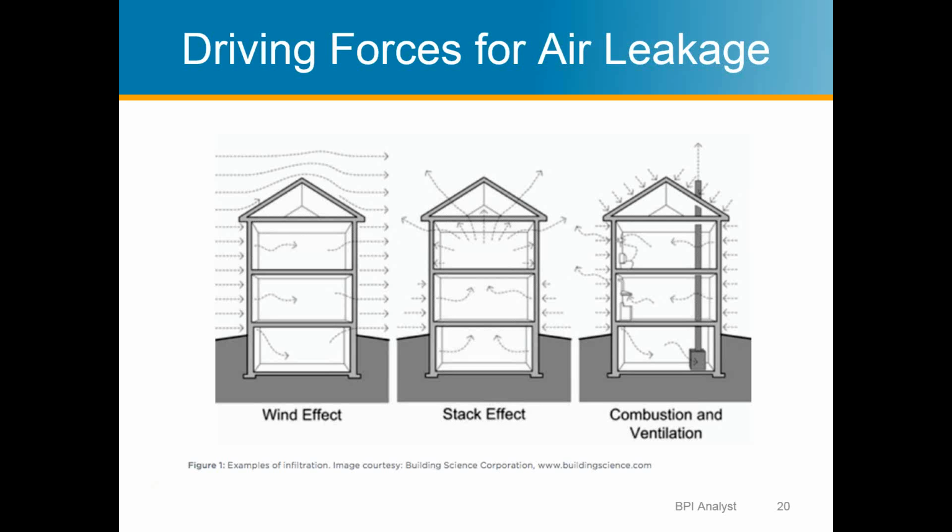So here on our house, two stories with a basement, the water heater has a vent pipe. Of course, if the water heater is running, hopefully the exhaust is going out. Well, that's causing a negative pressure inside the house. And so the air has to come in somewhere, and it's going to leak through the building shell and get into the house.